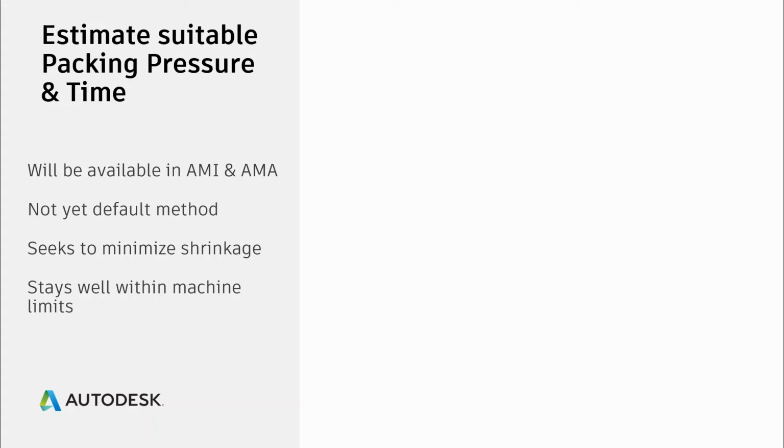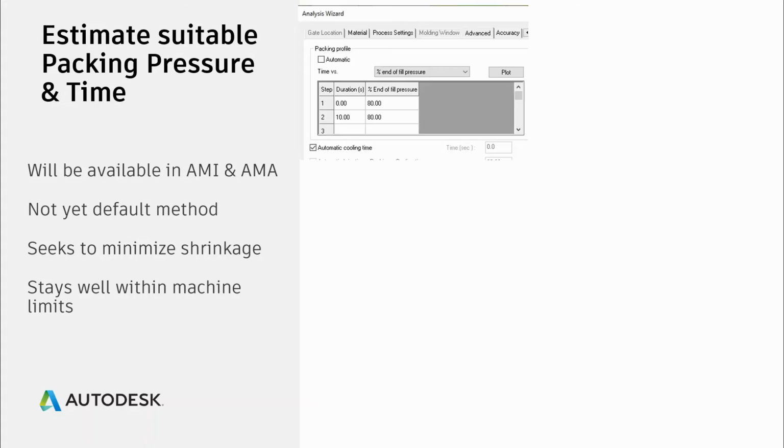Although it will not yet be the default method, we may make it the default method after we've received some feedback about how effective the method is. What the method does is that it seeks to minimize the shrinkage in the part while staying well within machine pressure limits. As an example, I'm going to show you now the interface for this automatic packing in Moldflow Advisor.